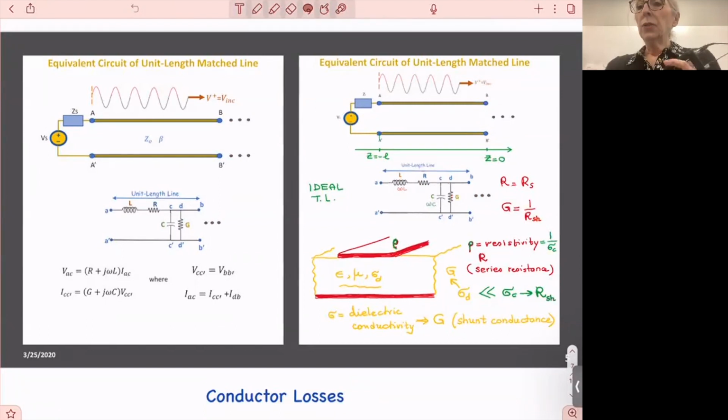So usually that comes in the form of the conductance, which is in parallel with the capacitance. All right, because you have the capacitance like this, the conductance is the better way to put the loss in here because it has the same units as the j omega C, the capacitance we see in the phasor domain.